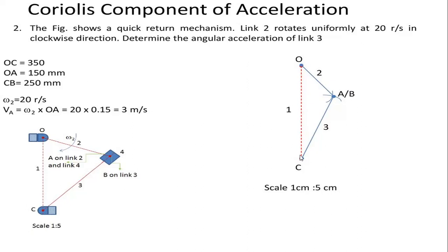Next, from the line point C as center, take length as 250 mm. So the second length is 250 mm, and by taking it in the compass, draw another arc intersecting the first line. That is the first intersection line. So we got the points A and B. The same point is connected to the two points, A and B. So we have drawn the space diagram.